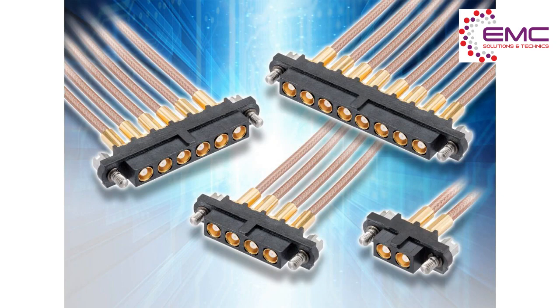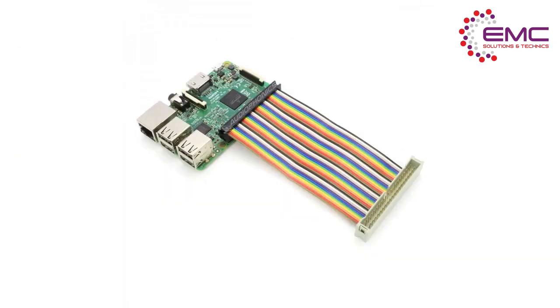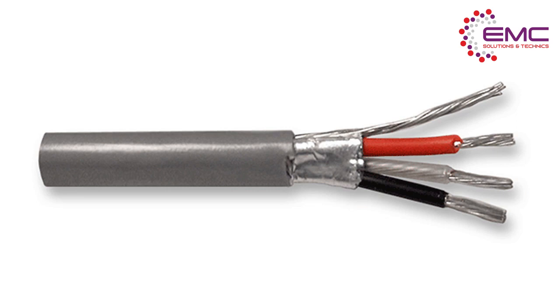Cables. Most EMC-related problems are caused by cables carrying digital signals that effectively act as an efficient antenna. Ideally, the current entering a cable leaves it at the other end. In reality, parasitic capacitance and inductance emit radiation. Using a twisted pair cable helps keep coupling to a low level by canceling any induced magnetic fields. When a ribbon cable is used, multiple ground return paths must be provided. For high-frequency signals and cables carrying switching currents, shielded cable must be used where the shielding is connected to ground both at the beginning and at the end of the cable.